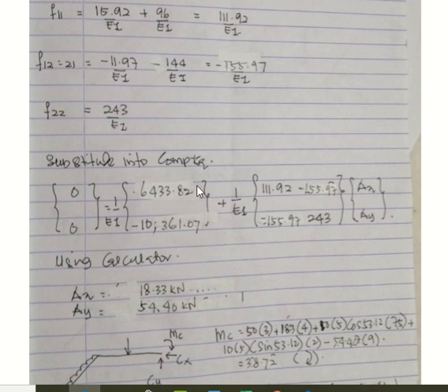After you substitute, your equation looks like this. Why are delta 1, delta 2 equal to 0? Because delta 1 and delta 2 are the deformation for the actual structure. Deformation for the actual structure is normally equal to 0 when there is no support movement, or no fabrication error for members. Okay, delta 10, delta 20, F11, F12, F21, F22. You substitute all of these values, then you can press your calculator.